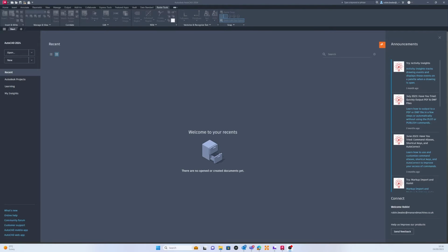In this short video, we're going to be looking at AutoCAD Raster Design. Now, Raster Design comes in both the AutoCAD Including Specialized Toolsets product, and therefore also in the AEC collection from Autodesk. That's the Architectural, Engineering and Construction collection. Raster Design sits inside of AutoCAD and offers you several additional tools to be able to take perhaps historical or legacy data that you might have a scan of or an image of and convert that into vectorized AutoCAD geometry.